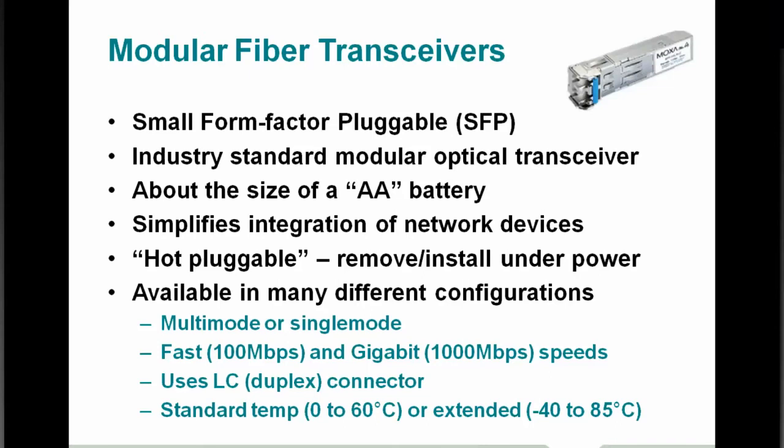And this has been hardened for industrial applications. It's about the size of a AA battery, and basically it plugs into a slot in your switch or your media converter and gives you that copper to fiber capability. It's also hot pluggable, which is kind of nice. So if there were a rare occurrence that the SFP had failed for some reason, you can unplug one, put in a replacement, and plug it in without having to turn off power to the actual media converter switch.